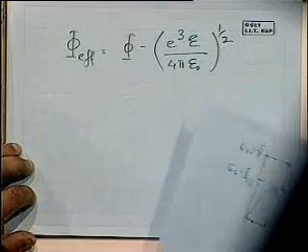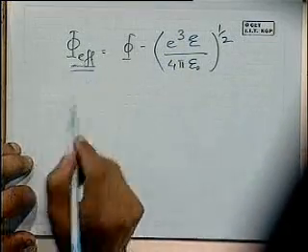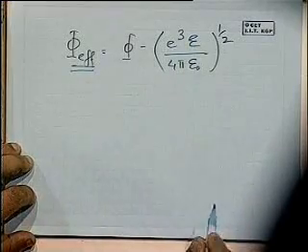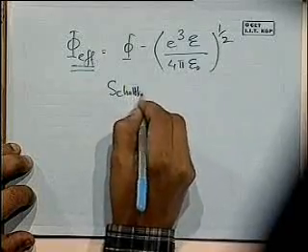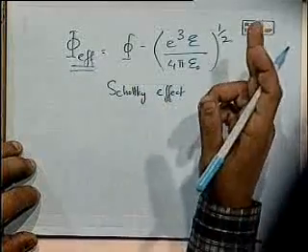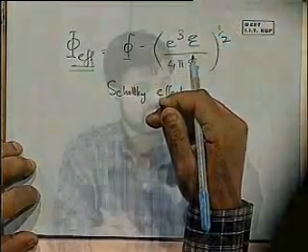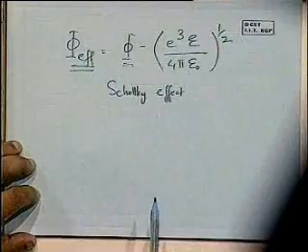We can get that from the previous equation, recombining it in terms to write it simply in terms of one effective barrier, phi effective. So this effect is known as the Schottky effect. That is the application of the external field enhancing the emission that is coming out, because the barrier is lowered from phi to phi effective by this amount.